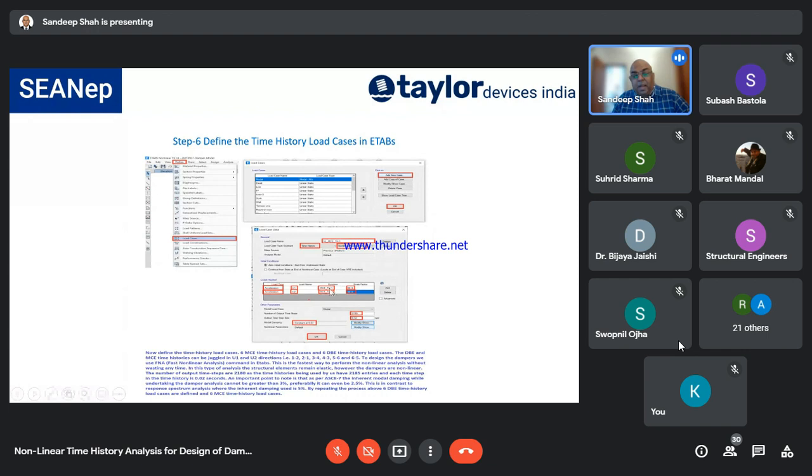Now over here I choose the function as MC time history 1, and over here I choose MC time history 2. Just be very careful, you can't choose the same value. That means I can't choose MC time history 1 and MC time history 1 over here, because that's going to produce resonance and it will give you totally different, inaccurate results, right? Depending upon what units are there in your earthquake model, you will put the scale factor. So over here the scale factor I've just used is 9810, which is nothing but the units for acceleration due to gravity.